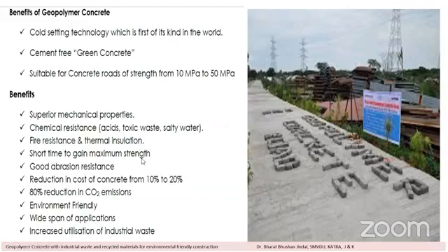Short time to gain maximum strength, good abrasion resistance, even a reduction in the cost of concrete by 10 to 20%, which is a major concern many times. Everybody asks whether it is costly or cost effective. Yes, it is cost effective. Nearly 80% reduction in carbon dioxide emission, so it is environmentally friendly. A wide span of application, as we have discussed so far, and increased utilization of industrial waste.